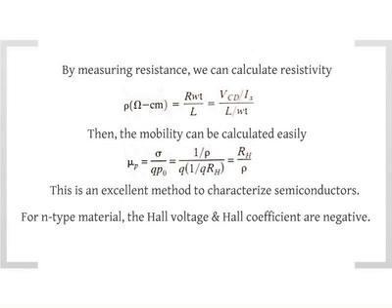We can also measure the resistance of the bar, right? That's very simple. That's just what we did here. You come back to this model, you know the applied voltage, you know the current because you can measure these with an ammeter and voltmeter. From Ohm's law, you know what the resistance is, V over I. From resistance and this expression, you can compute the sigma because you know these dimensions can be measured very accurately, the length and the area and so on. You can calculate resistivity or the conductivity.